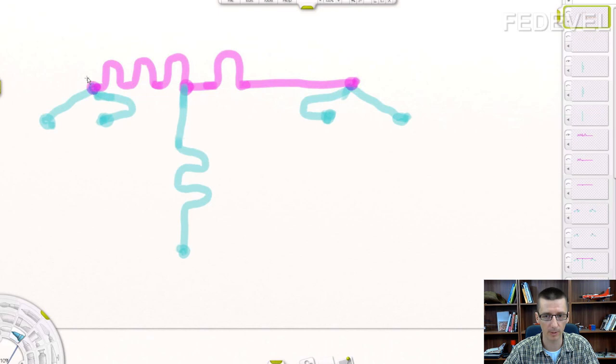Because the length between this wire to this wire has to be exactly the same as the length from this wire to this wire. So if we take the length from here and put it on this segment, we have to put it also on this other segment. Sometimes there is space around these tracks, so you can do this. But always consider if it's better to put the waves here or here.